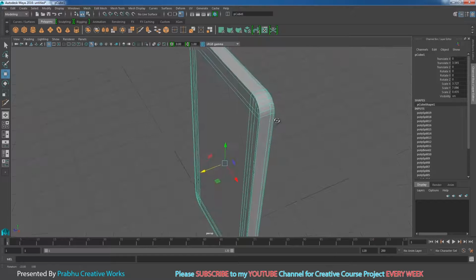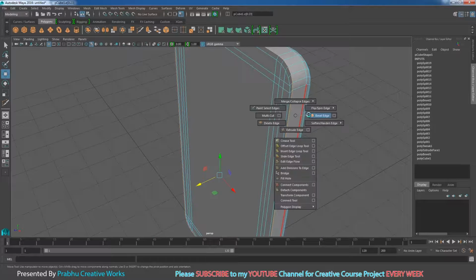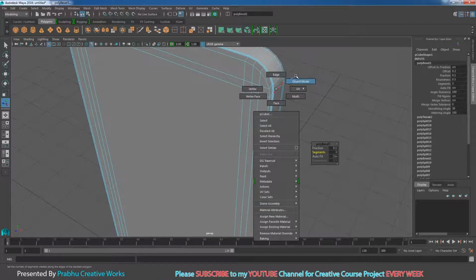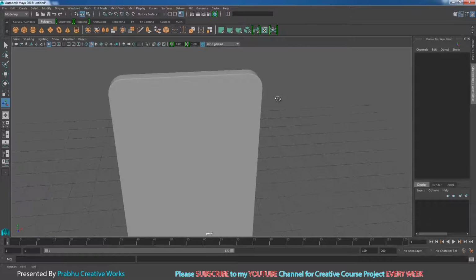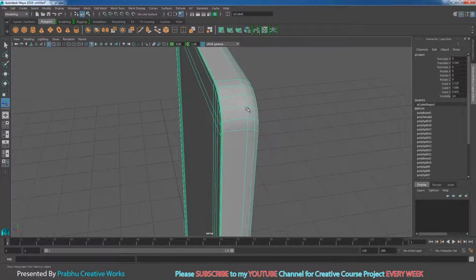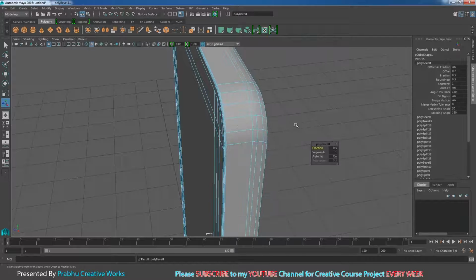So now I want to make details over here. So double click on this edge, shift right click and choose bevel edge. So I will decrease my fraction to 0.1 and increase segments to 3. So like this. Now I want to make, sorry, double click on this edge, shift right click and choose bevel edge. So you want to go over here, channel box and layer editor, and decrease the fraction amount to 0.05. So very thin.